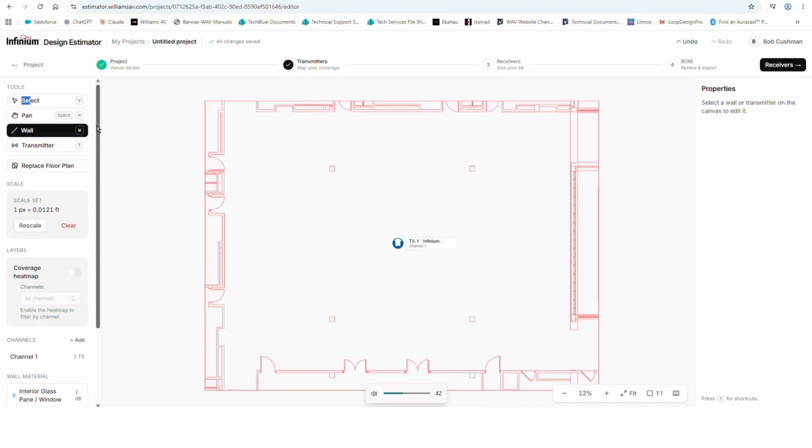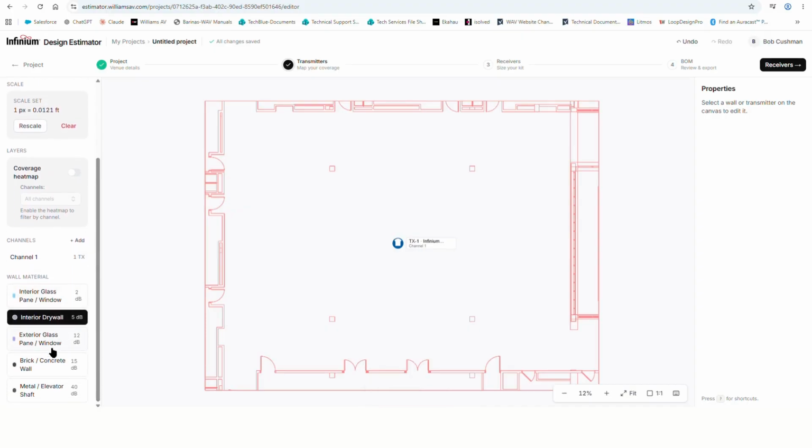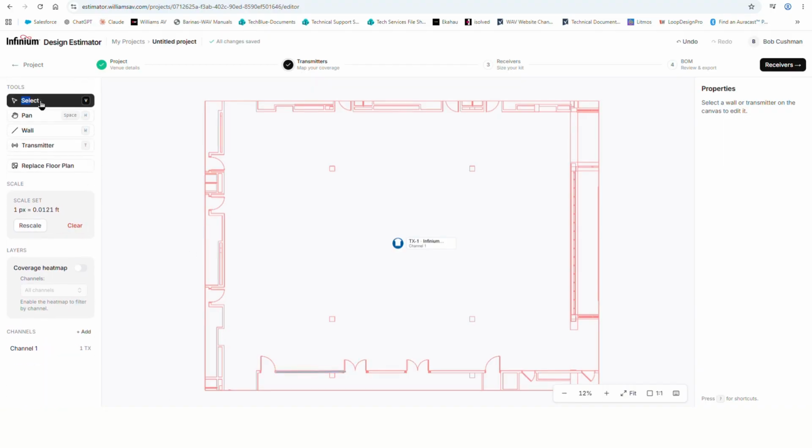Now select and trace the chosen material. While tracing, if an error is made, use the escape key to exit out of the trace. To finish tracing, hit the Enter key. To delete a trace, select it and then use the Delete key to delete it.